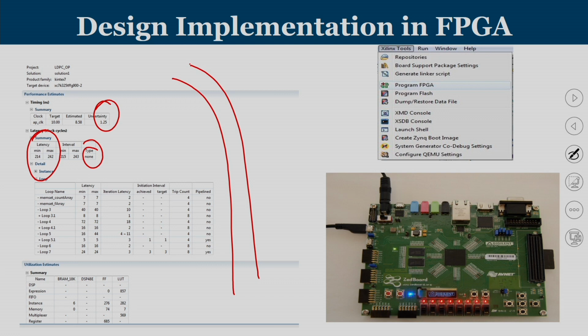Once you get the bit stream, you have to program it onto the FPGA. You can use the FPGA board, where the design that you developed inside your computer is transferred into the FPGA board, and the board now models, let's say, your D-bar router or MinBD router or Chipper router. There are pins and knobs available. Through these pins and LEDs, you can give some input, maybe a packet number or a destination number, and verify whether they are giving the appropriate results or not.